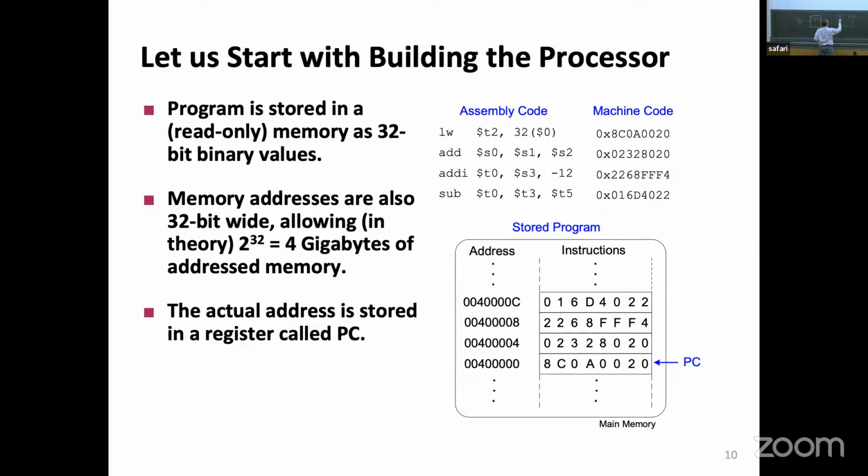Now the second one is similar. This will be the address 2. It will be again 5 bits. And this output will be read 2, again 32-bit. What else do we have? Well, we are going to have a third address. We are not talking about it right now. And we are also going to have a write data that we need to write things back to. And certainly this is at some point also going to have a clock. Now, this is another 5 bits, and this will be 32.